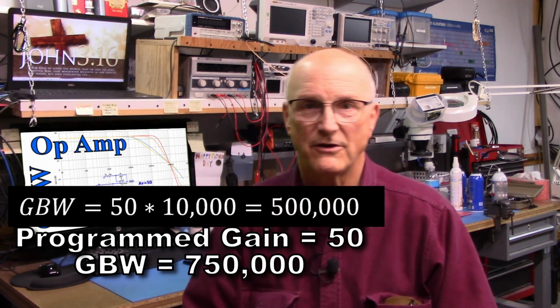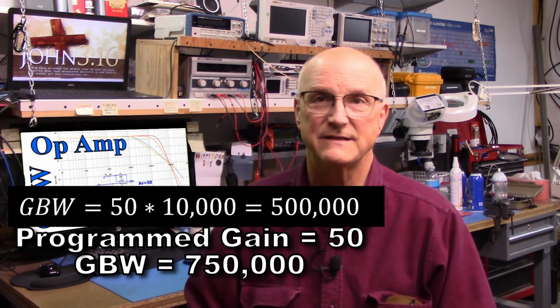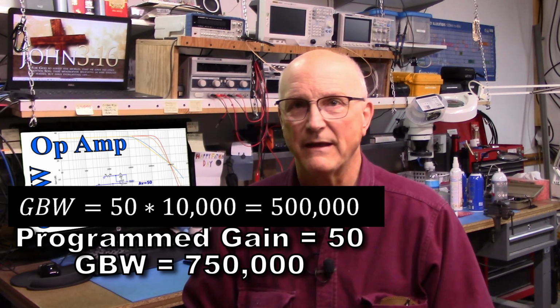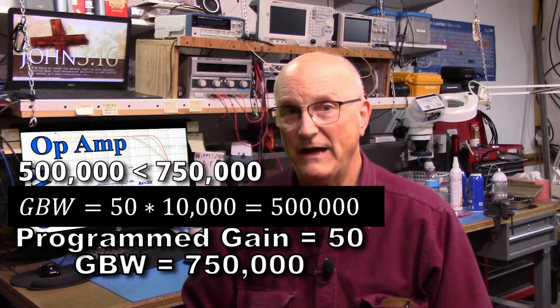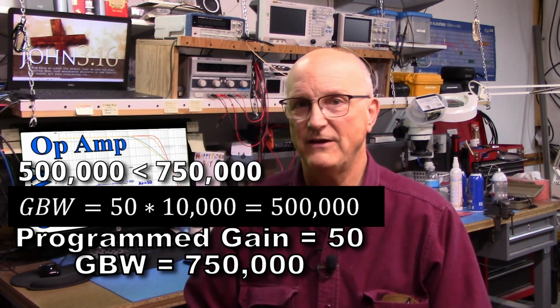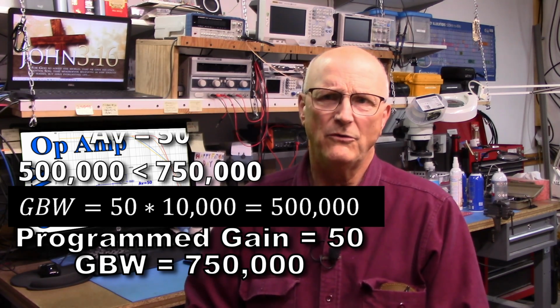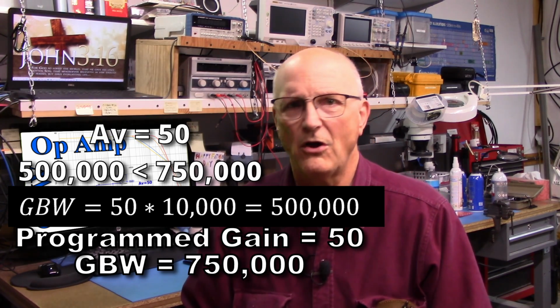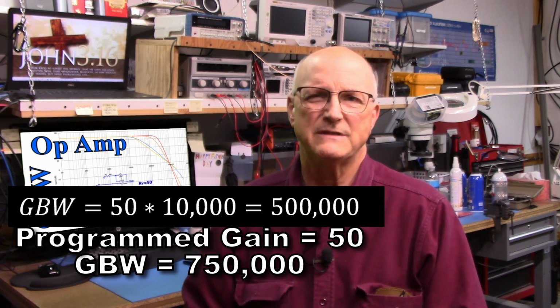At 10 kilohertz, the product of the programmed gain and the frequency is 10,000 times 50, which gives us 500,000. 500,000 also does not exceed the gain bandwidth product of 750,000, so the gain of our amplifier will also be 50. But what about at a frequency of 100,000?